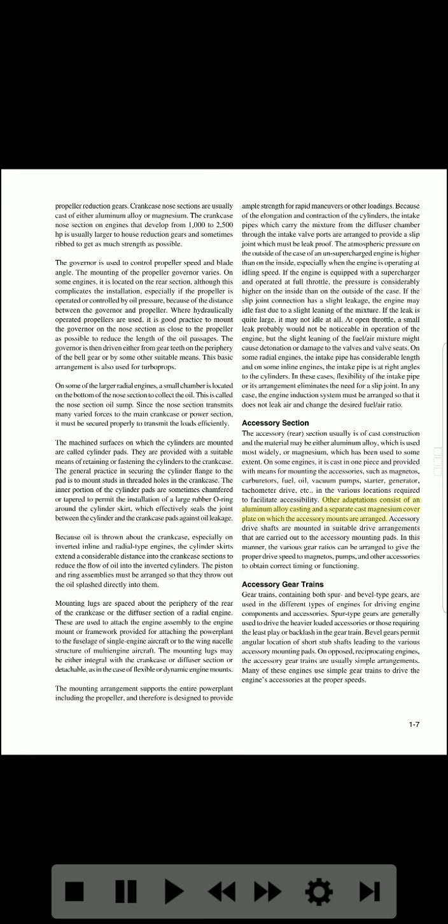Other adaptations consist of an aluminum alloy casting, and a separate cast magnesium cover plate on which the accessory mounts are arranged. Accessory drive shafts are mounted in suitable drive arrangements that are carried out to the accessory mounting pads. In this manner, the various gear ratios can be arranged to give the proper drive speed to magnetos, pumps, and other accessories to obtain correct timing or functioning.